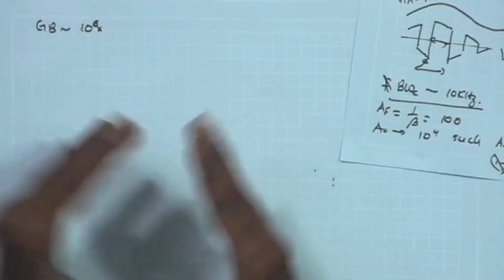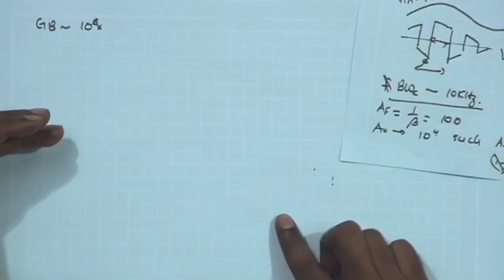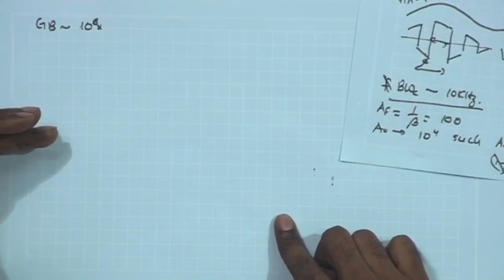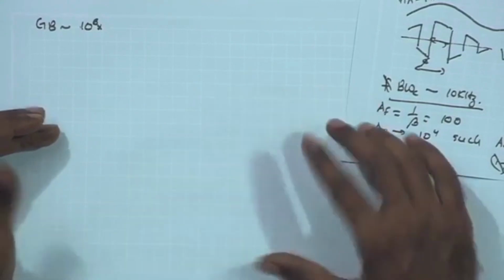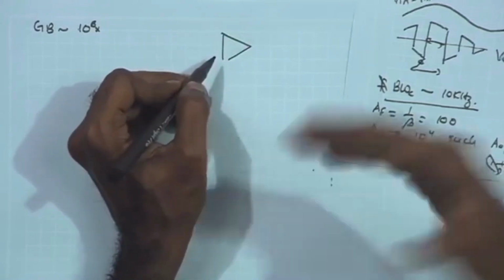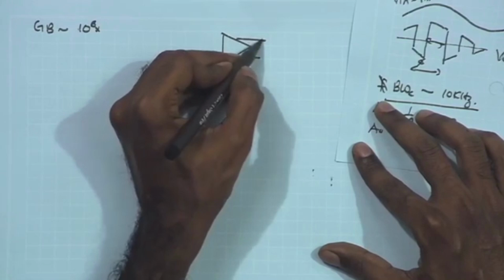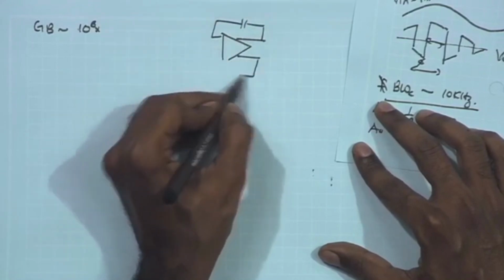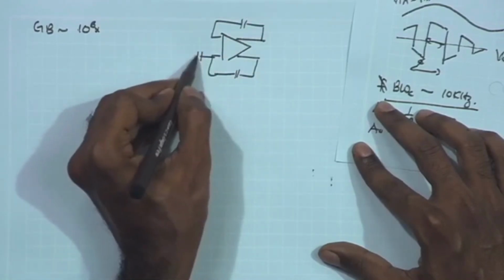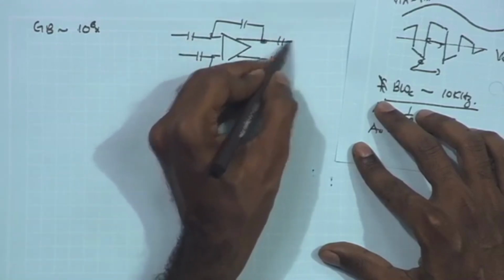One of the inputs required to do the calculation will be the load capacitance. What is the load capacitance faced by that amplifier? And towards that end, again we have discussed that the load capacitance ultimately for the overall differential operation depends upon the next stage input capacitance. So you may be having the next stage input capacitance acting as the load capacitance of this stage.